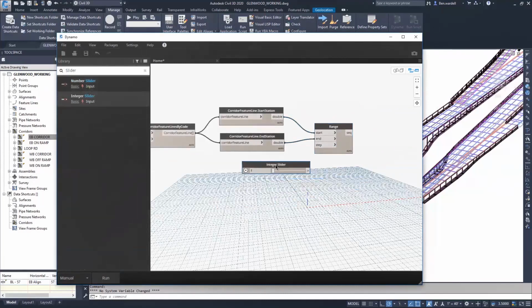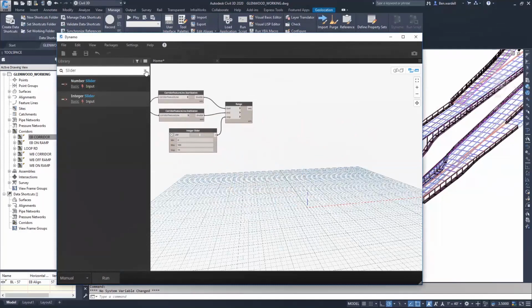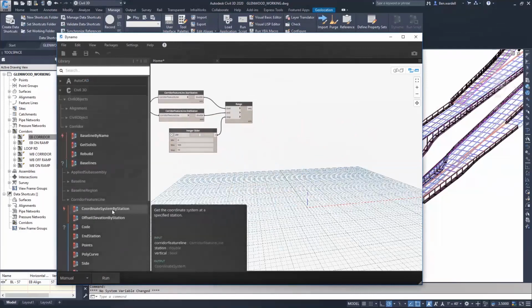So let's say maybe you want to have them at 500 meters, 200 meters along the corridor. But in this case, it is preferred if you just leave it and use a slider. If I see that 200 is more frequent or they are closely spaced, I'll be sliding to lower the number or sliding to increase the number. So by starting with a default value of 200, you should be able to see how frequent 200 appears on that particular corridor model you are looking at.